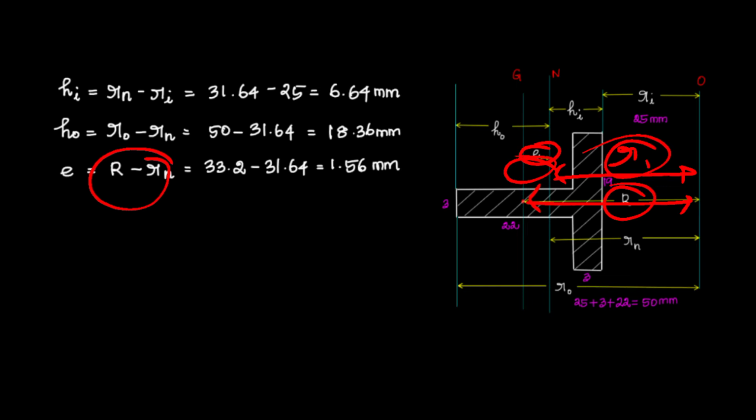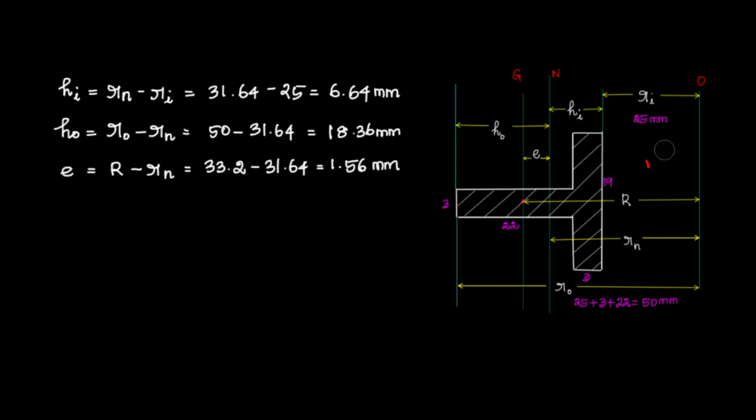Okay, let me see what are the different stresses acting on the curved beam. Okay, so in page number 6.3, using the diagram and formula given, we can find the Rn value and the capital R value. Why do we find these? Because we need to calculate the load value, and to calculate the load value we need the stress value. Stress is load by area.